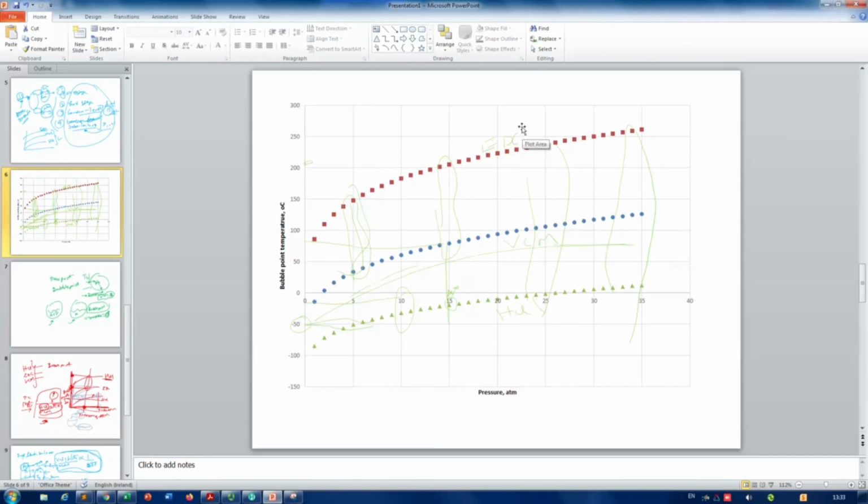So that's the deal. And then we will try to do that at the same pressure, 15 atmosphere, sorry, the pressure, and then we will try to raise the temperature of the reboiler in order to evaporate your vinyl chloride monomer, and then you will collect vinyl chloride monomer in the top.